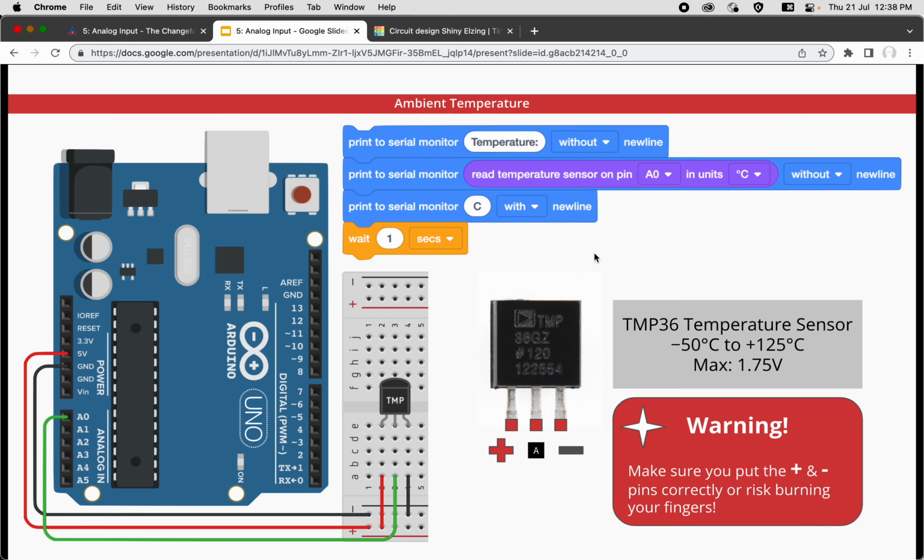We are going to go back here. So the temperature sensor senses about -50 to +125 degrees Celsius. That is the range. When you plonk in these, they are just decorative, so I make it look nicer. We don't want it to spam too much, so we wait 1 second. And the legs are positive, this to the A0, and then this is negative.